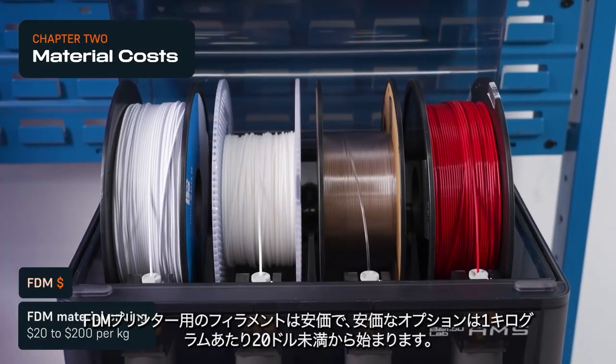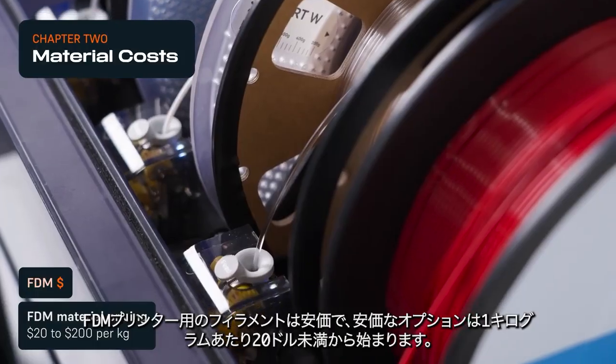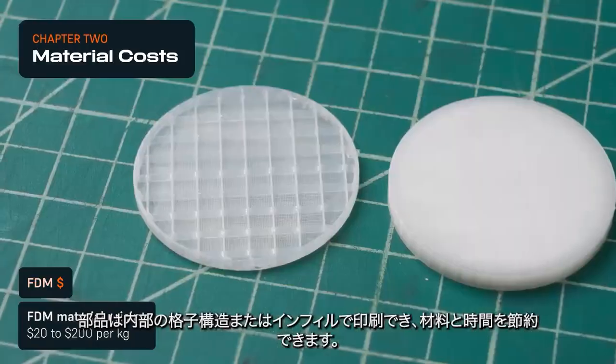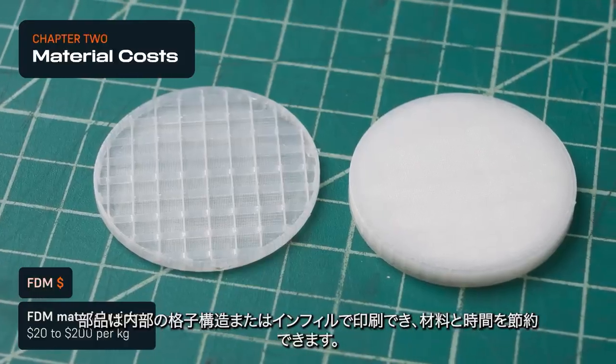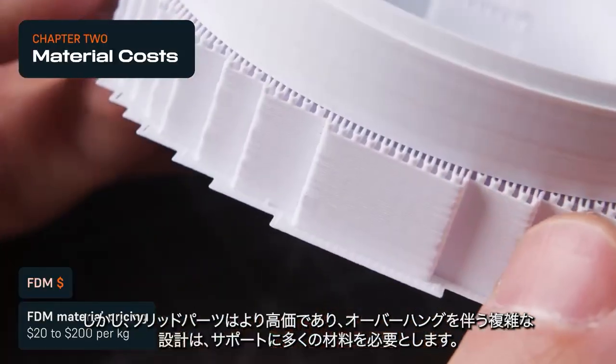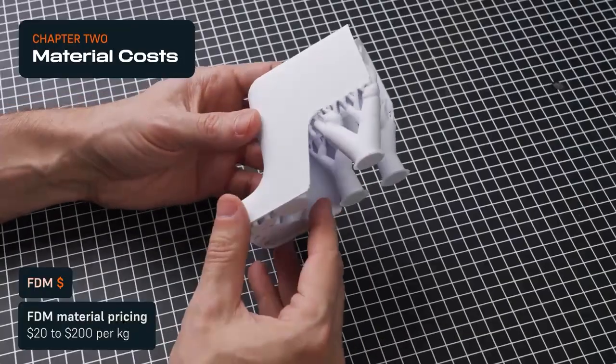Filament for FDM printers is inexpensive, with budget options starting under $20 per kilogram. Parts can be printed with an interior lattice or infill to save material and time. However, solid parts are more expensive, and complex designs with overhangs require a lot of material for supports.